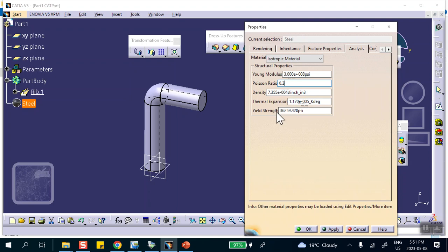This is not correct because the yield strength of the material depends on its heat treatment. Yield strength of structural steel is about 30,000 psi, like that. But for something that's used in a destroyer or a submarine, it goes up to 100,000 psi. So anyway, this number is never used. This number is there; it's never used. If you want, you can change it. It's never used. Okay, good.